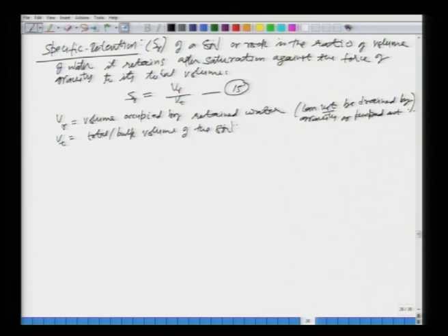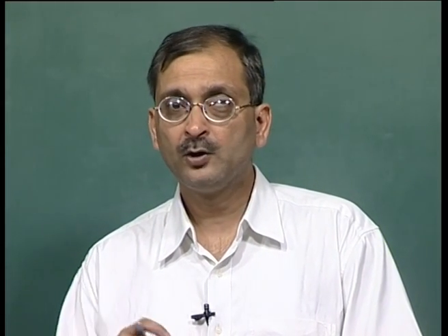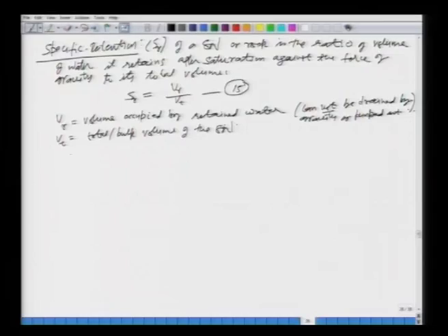Basically, this parameter gives us some idea about how much water cannot be extracted, and the retention capacity of different types of soils will be different. Depending upon that, if we have some idea, we know how much water we are actually going to play with if we have an aquifer of a certain volume available to us.